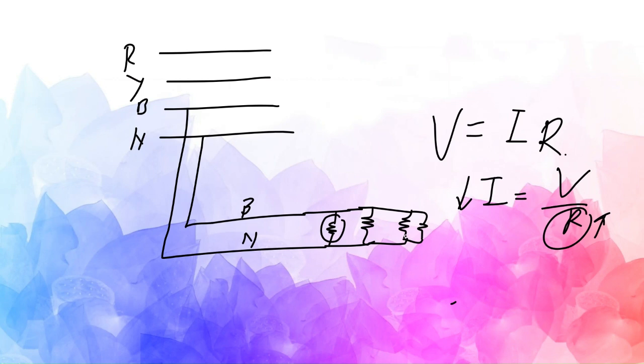I was working in one of a very large IT park as a maintenance in charge, and I have seen many people just don't understand whether the lamps are in series or in parallel, and they are confused about it. So you need to understand that since all these circuits are in parallel, when I'm adding load, what is happening?